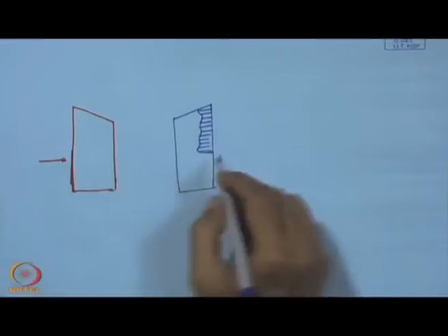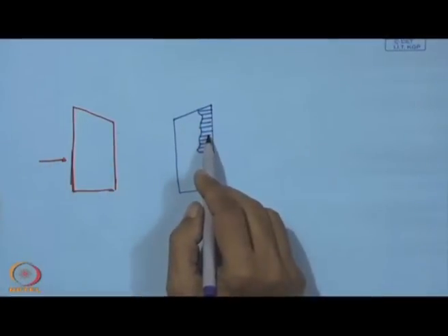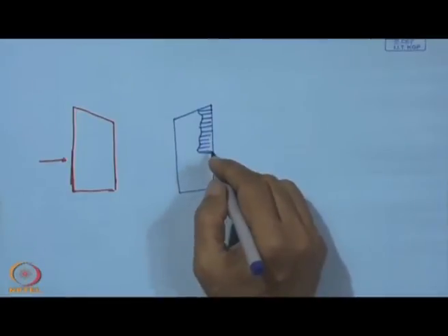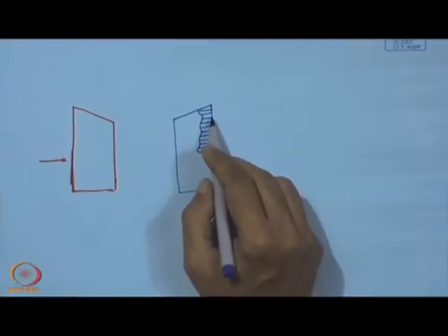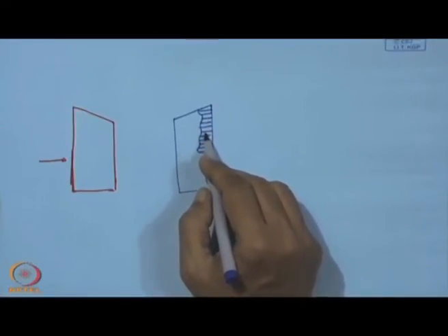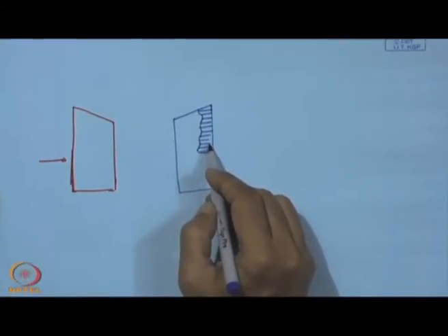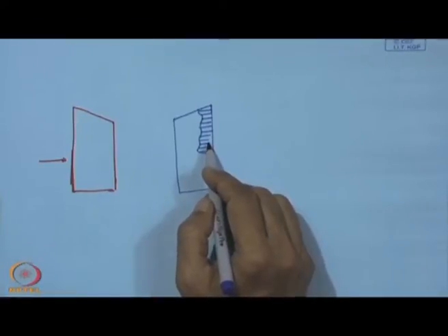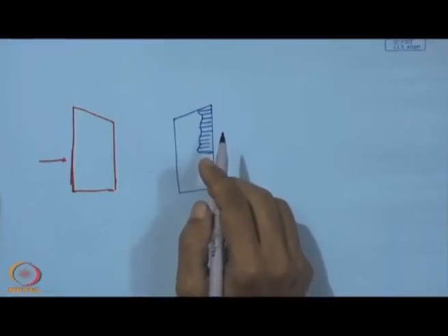That means, over this contact zone, this wear on the flank has taken place because of the severe rubbing between the workpiece and the side surface of the tool, and this surface here becomes parallel to the direction of velocity and clearance is 0. In that case that will simply lead to rubbing, the area will increase, the force will increase, and that may lead to vibration, and that is why we do not allow this tool to operate for a longer period of time.